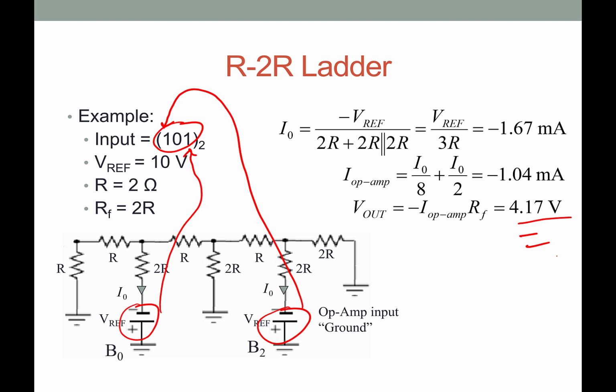Now remember, with the digital to analog converter, you're converting a particular digital value to an analog voltage. So you have this same kind of resolution. You can't get any analog voltage that you want out of it, but the more bits you have to use, the more discrete levels of output voltage you can get.